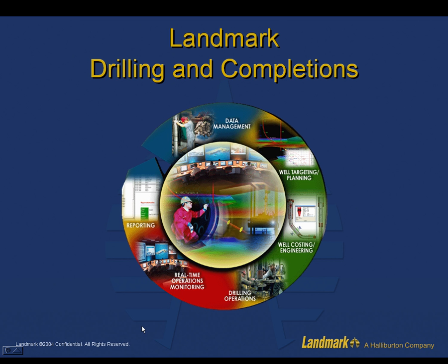In summary, you've seen how we've started by designing a trajectory in Compass and sharing that trajectory information with Casing Seat. We entered pore pressure and fracture gradient information in Casing Seat, determined the Casing Seat locations, and then moved into Stress Check for a detailed casing and liner design. We capitalized on that design and WellPlan for the planning phase. We quickly looked at a drag chart using all the information that was previously populated in the other applications. We also used WellPlan to take actual data from OpenWells to make use of it, analyze the situation, and come back with some recommendations.